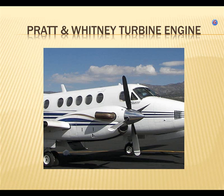The other thing that variable pitch props do is maintain a constant speed of the engine. So if you set the engine to turn at 3,000 RPM and in flight you want to change the pitch, it changes in such a way that it keeps the RPM of the engine the same. It's called a constant speed prop. That's also the same thing as a variable pitch prop. It's called constant speed.